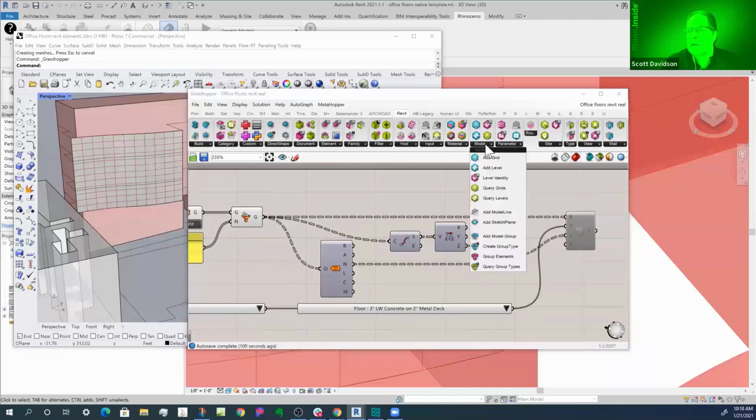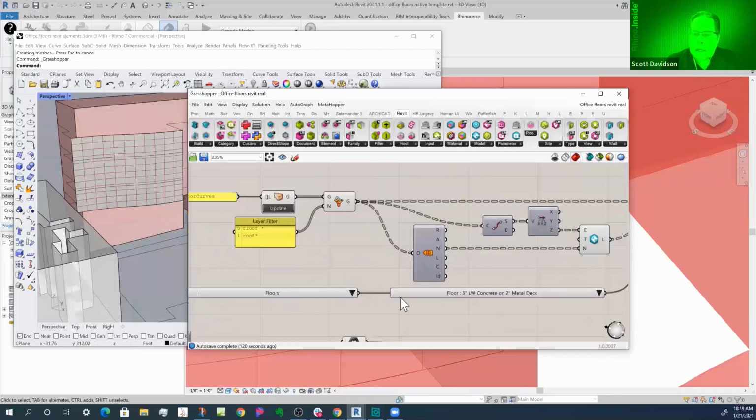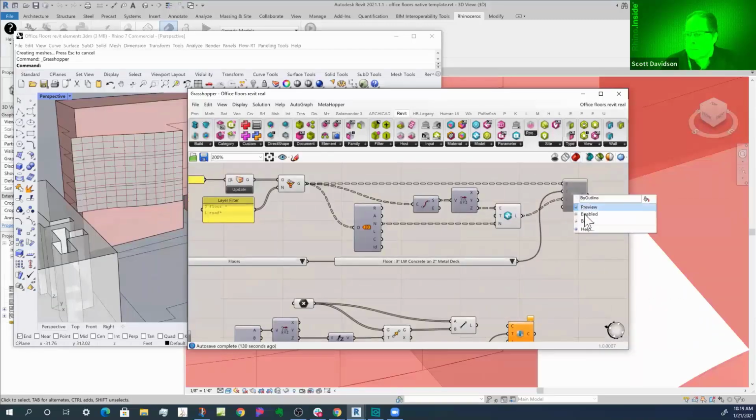So we go over here to, I have our level. I can add a level, and then it creates that level, named that, and at the same time, it's going to create a floor, which is a native floor using a standard type in Revit. Here's all the types that happen to be in this model. And then I'll just enable this here.